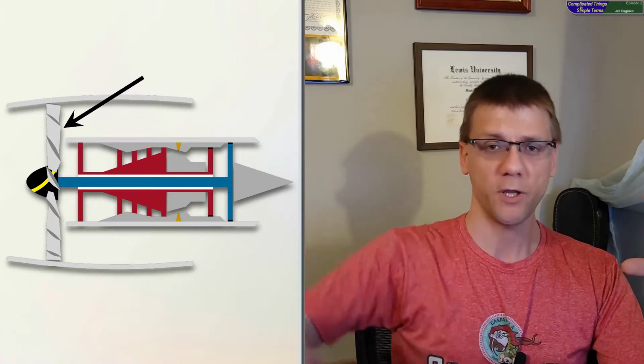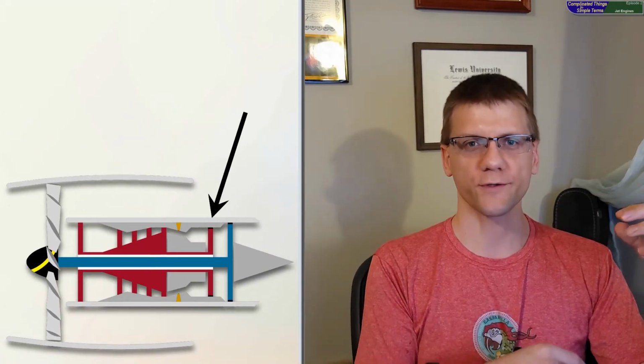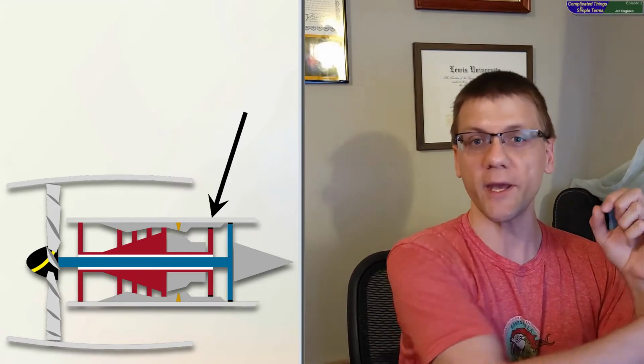Well, all they've done is put another turbine behind the first one and have a second shaft that runs through the first shaft, and that's connected to the big fan in the front. So as this hot exhaust goes out the back of the engine, it goes through 2 turbines. The first turbine takes the brunt of the explosive force of this constant ignition of fuel and air as it's exhausted out the back of the engine.